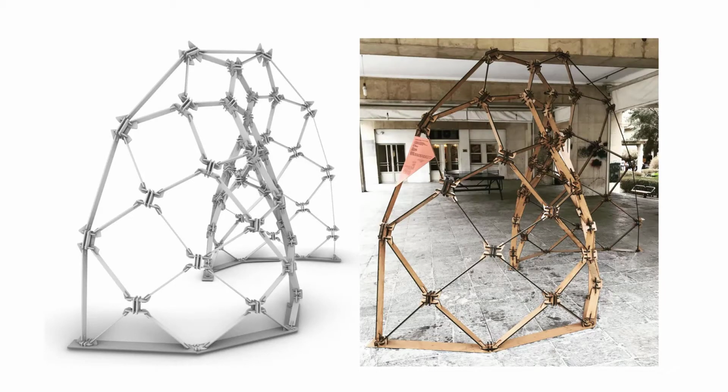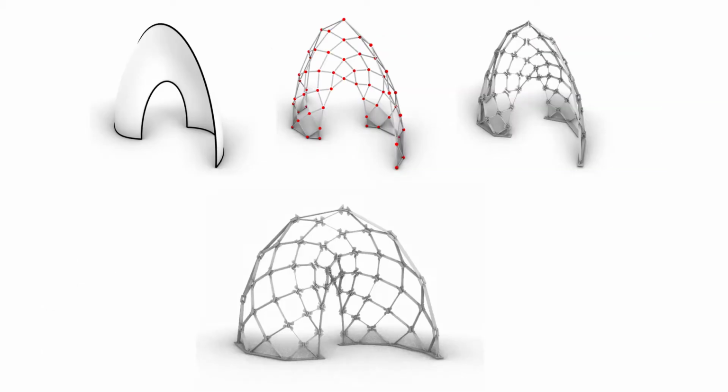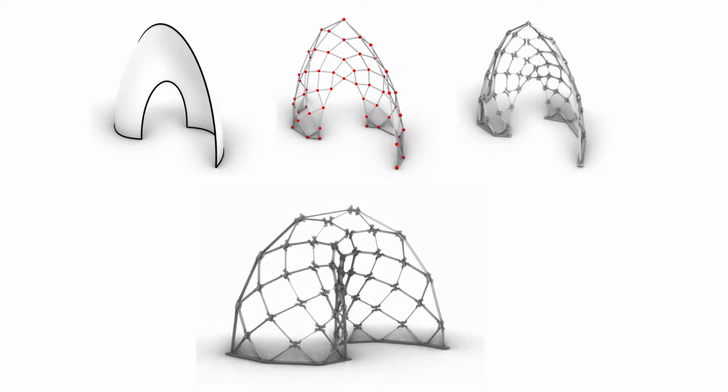After designing the node system, we designed and fabricated an architectural scale pavilion to visualize its application. The overall geometry of Twisted Eye Pavilion was designed as a double curved surface in order to show the capability of the node system with different complex shapes. Nodes behave desirably regarding the torsion of the base network. The entire structure behaves as a self-supporting structure under the dead loads.